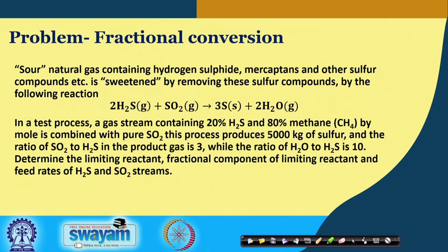We have the hydrogen sulfide, which needs to be removed because if it reacts with water it forms mild acids, and because of this the pipelines or the equipment through which the raw natural gas passes would get corroded. So we need to take out this gas, and not only that, other sulfur compounds like mercaptans. And what are mercaptans? Mercaptans are compounds of sulfur which are hydrocarbon in nature.